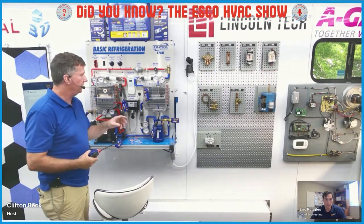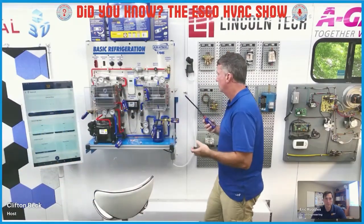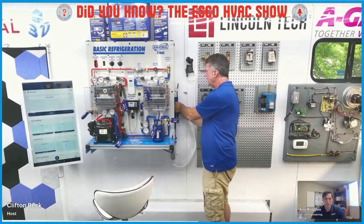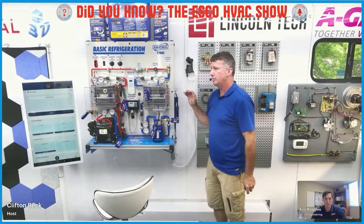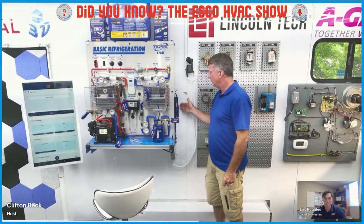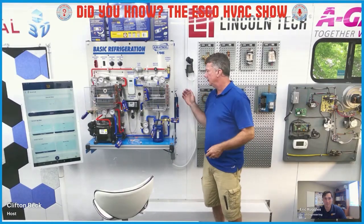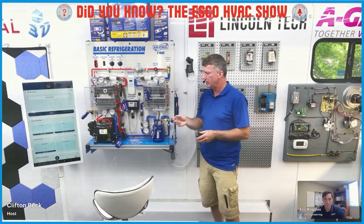So on this particular unit, you can see here, this one is labeled as our evaporator. So I'm actually going to go ahead and put this one on the back of the system, right in front of the fan. You can't see the fan from your perspective, but there is a fan on the backside and a fan shroud so that we can measure our incoming air using our temperature, humidity, as well as on that supply side.